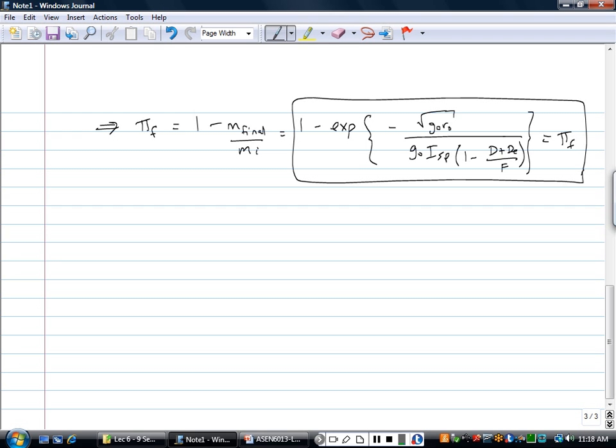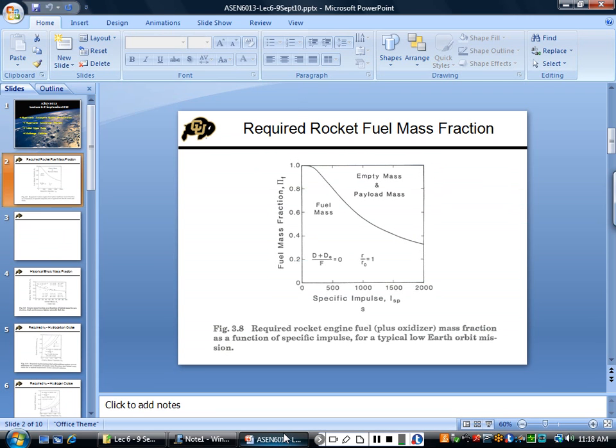For rockets specifically, thrust to drag is a lot easier to work out than for an air-breathing system, which is a lot more complex. So in this case, you actually can boil this equation down to something you can do sensitivity analysis on much more easily, because it's more fundamental than the air-breathing case. But if we look at the nuance of what this looks like now,